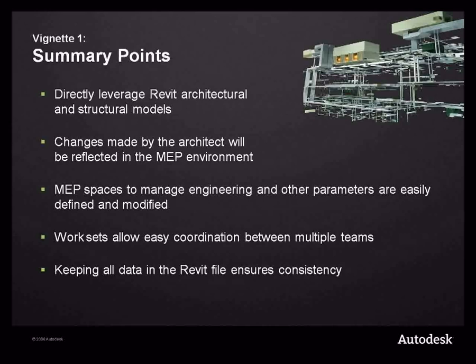If you're starting with the Revit architecture model, you can get started immediately because Revit MEP can leverage the same architectural model. By linking the architectural model, changes made by the architect can be immediately reflected in the MEP environment. Within Revit MEP, spaces are defined to enable the engineer to perform building energy and lighting analysis. Revit MEP has powerful tools to allow you to quickly create and manage spaces and zones.